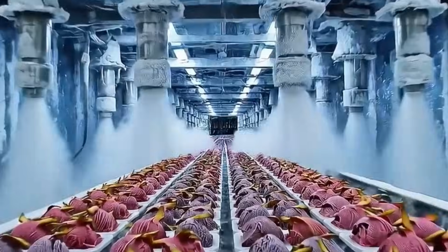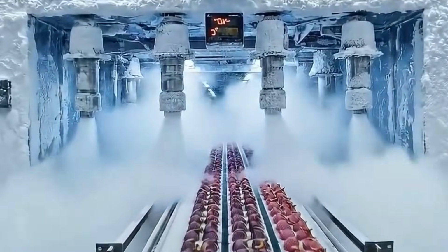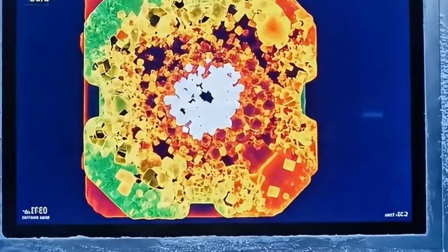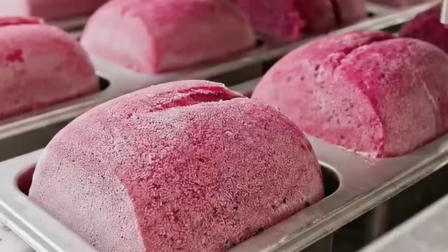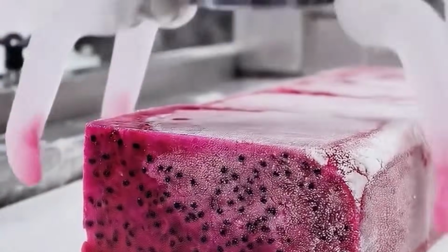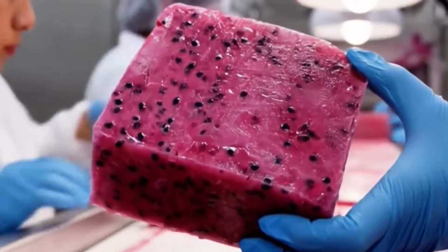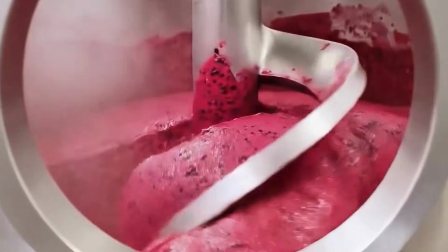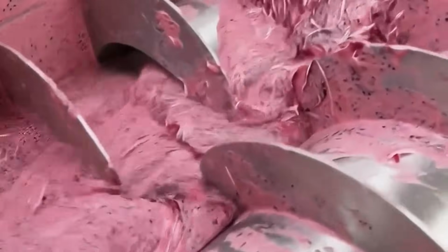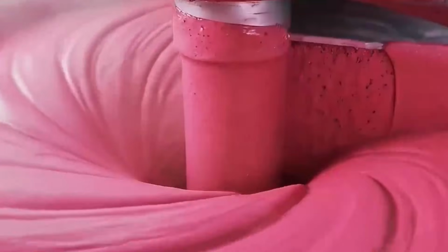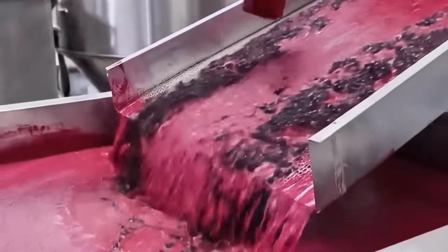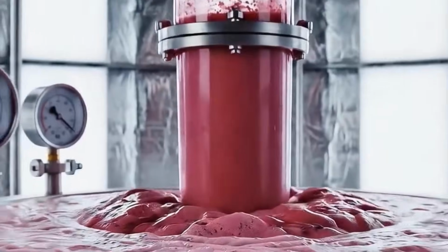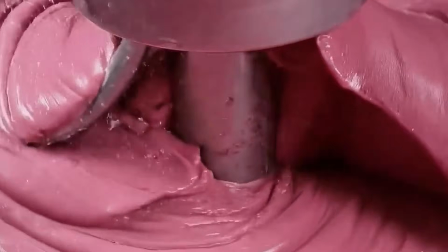Filled containers are sealed with pre-cut lids or heat-sealed films. Lidding stations use servo-driven arms and apply uniform pressure to ensure adherence. Date coding and batch marking are applied using thermal inkjet or CO2 laser systems immediately after sealing. Each pack is passed through a metal detector, which uses multi-frequency coils to detect foreign metallic objects within the sealed product. Immediately post-packaging, the product enters the hardening tunnel.